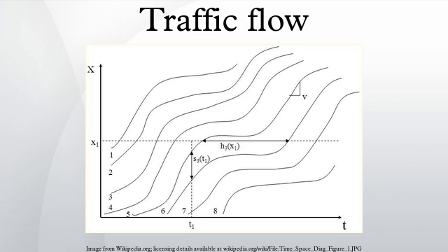Kerner's three-phase traffic theory. Kerner's three-phase traffic theory is an alternative theory of traffic flow. Probably the most important result of the three-phase theory is that at any time instance there is a range of highway capacities of free flow at a bottleneck. The capacity ranges between some maximum and minimum capacities. The range of highway capacities of free flow at the bottleneck in three-phase traffic theory contradicts fundamentally classical traffic theories as well as methods for traffic management and traffic control, which at any time instant assume the existence of a particular deterministic or stochastic highway capacity of free flow at the bottleneck.